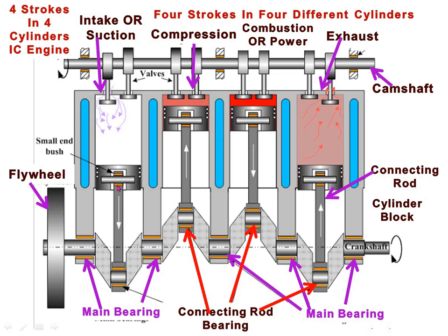See, this is the suction stroke, or we can say intake stroke. During the intake stroke, the inlet valve opens and the exhaust valve closes. So, due to the downward movement of the piston, air is introduced inside the cylinder. After that, the piston travels from bottom dead center to top dead center, and at that time both the valves are closed, and the air introduced during the suction stroke is compressed in the engine cylinder. So this is the compression stroke.